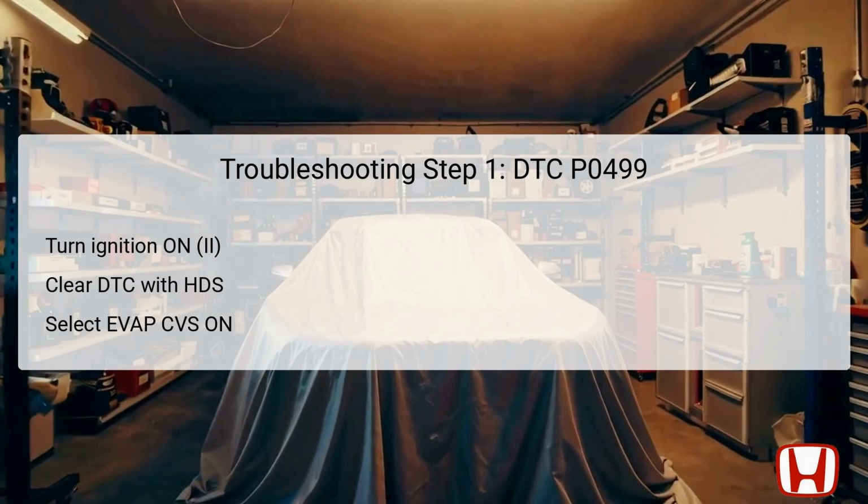After clearing the codes, you will select the option for EVAP Canister Vent Shut Valve, CVS, ON in the inspection menu of the HDS. This prepares the system for further diagnostics by testing the valve and its associated circuitry.